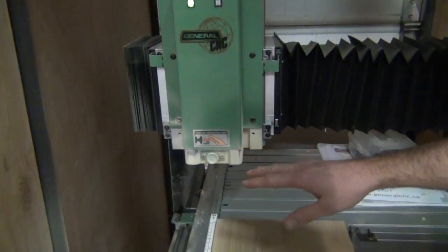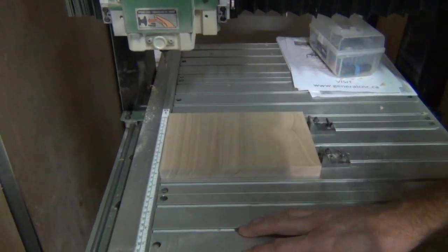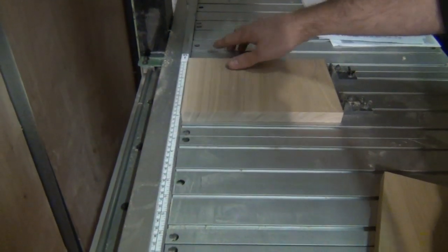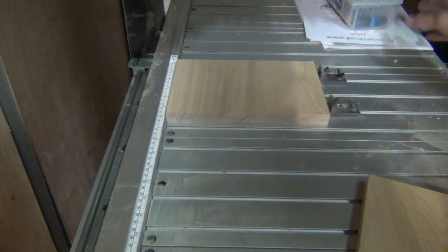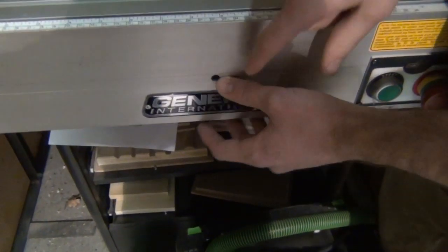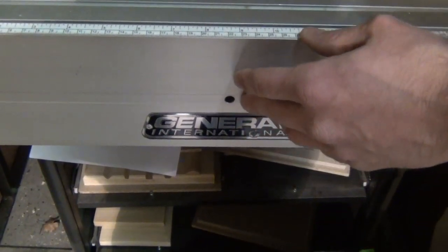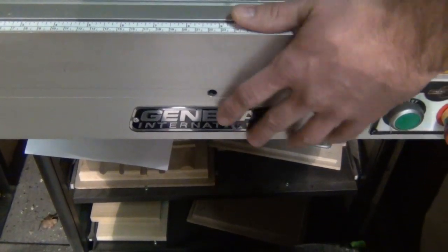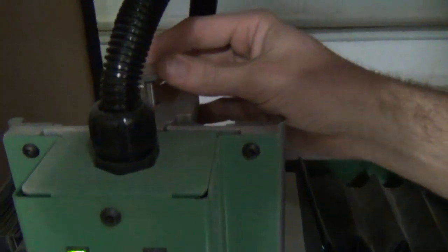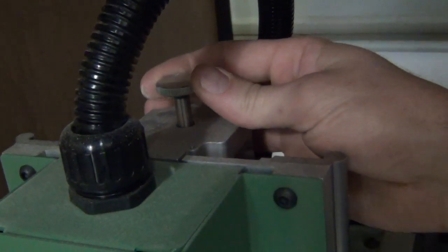This particular CNC is really cool. It's equipped with a safety mechanism, so it won't let you go beyond certain parameters. So if I push my Y plus and I go back here too much, it shuts the machine off. And then I pull out my little tool, and there's a little hole down here, and I'd use my Allen wrench, and I'd bring the CNC forward until we were past the safety zone. And there's one of those on this side, so if I get too aggressive on a cut and it stalls out, I can just bring the head up with that right there.